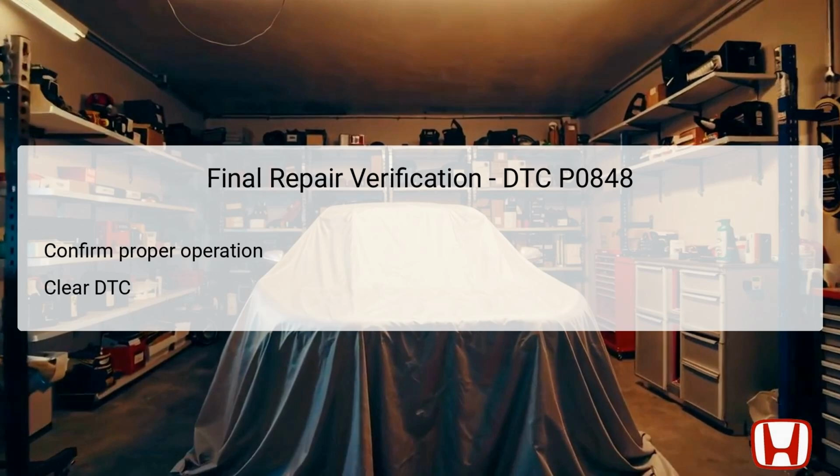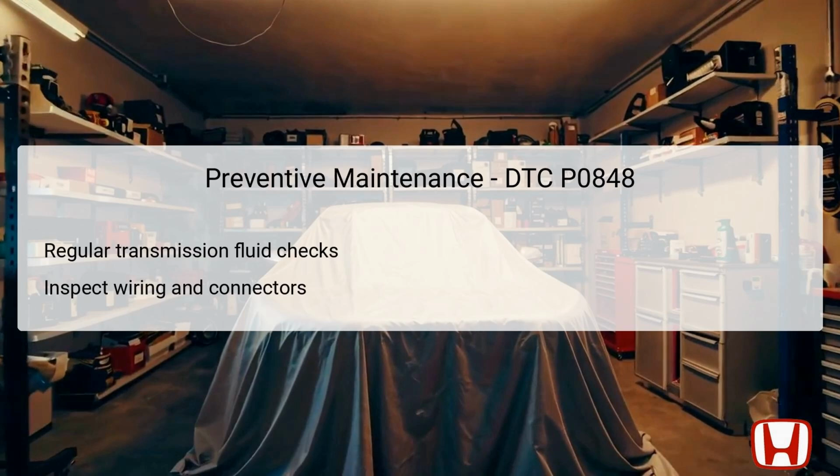Preventive maintenance plays a crucial role in avoiding future occurrences of DTC P0848. Regularly checking transmission fluid levels is essential, as low fluid can compromise hydraulic pressure necessary for the function of the transmission components, including the transmission fluid pressure switch B. Ensuring that the transmission fluid is at appropriate levels and in good condition helps maintain optimal performance.